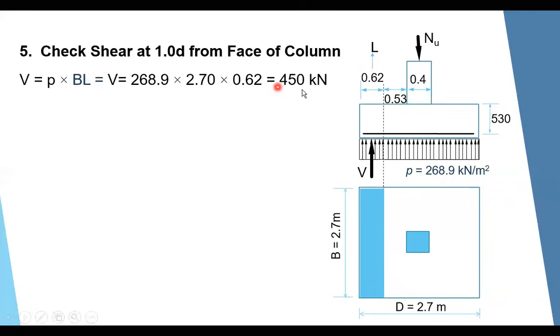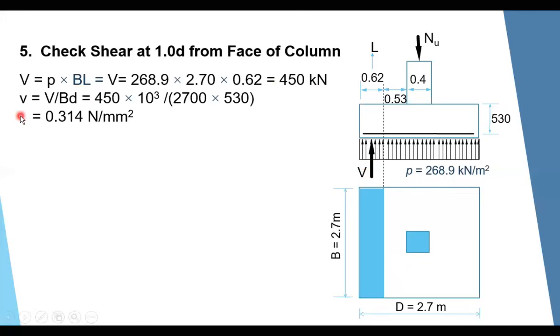This one is the shear force that we need to use to get the shear stress. So the shear force is 450 kilonewton. To get the shear stress, it equals the shear force divided by the shear area. So it will be divided by this width here times D.